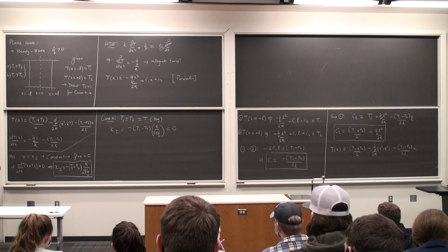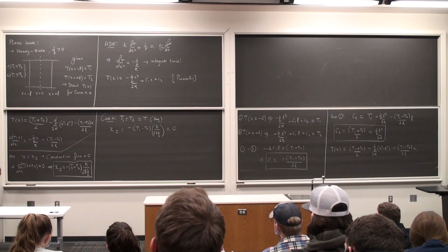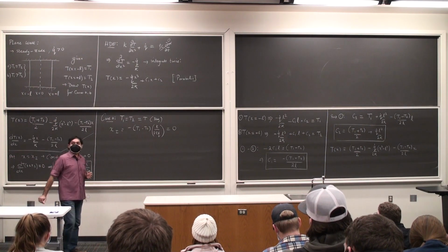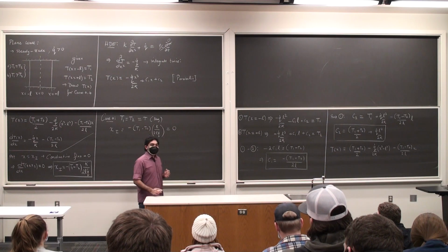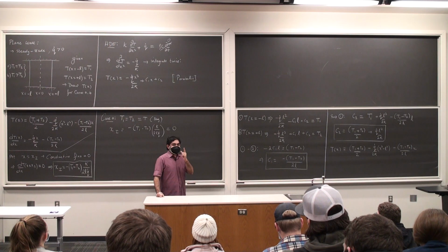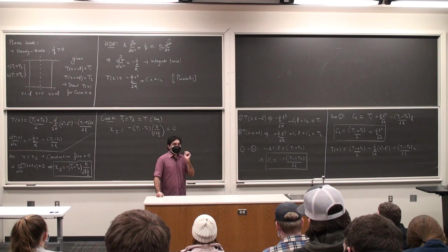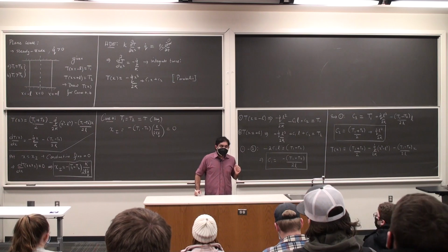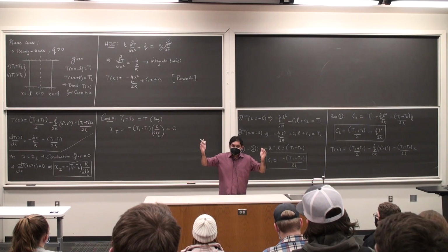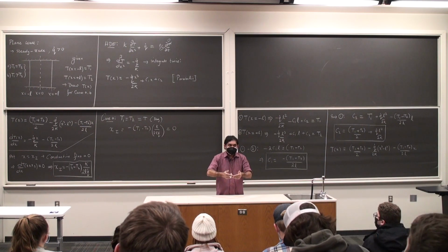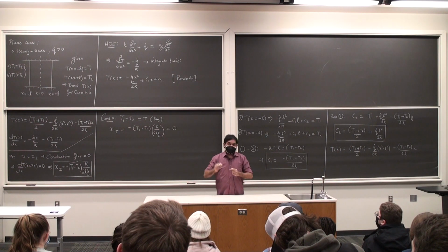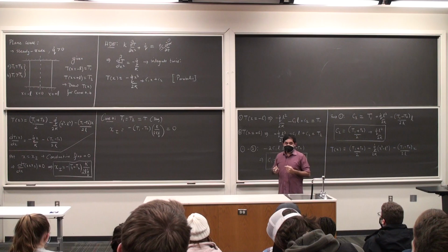My question to you, without doing the calculations, I'm going to do it. What is the direction of heat transfer? Is it from the left to the right or right to the left? Or is it something else? Center outwards. It has to always start from the center, go outward. That's what you're saying. Could it be a different situation? Could I have heat coming in from both sides and then joining at the center and becoming equal to 0? Could I have that? Yeah, for a negative generation. Yes, nice.